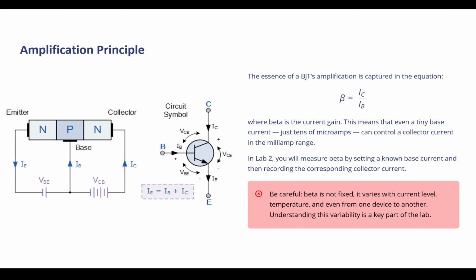Unlike the MOSFET, where the gate was isolated and there was no participation of current from the gate, the base in a BJT is directly connected to the semiconductor. So whatever charges you toss in from the base, like in a KCL scenario, would affect the amount of current that passes through the semiconductor.